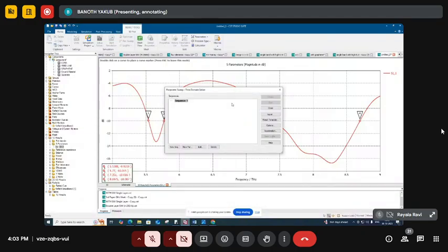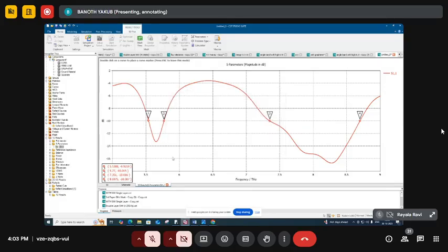After clicking OK, 10 linear values from 0.1 up to 1, the parametric analysis will be done. After that you can see the responses at 0.1, and how the chemical potential works on the graphene material, the tunability responses we can get at 0.1, 0.2 up to 1. This is how to do parametric analysis. So the time is almost 4.